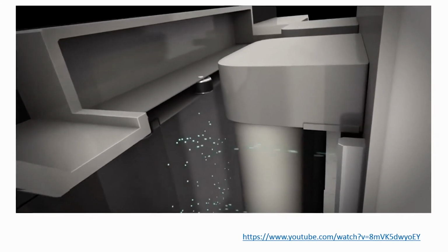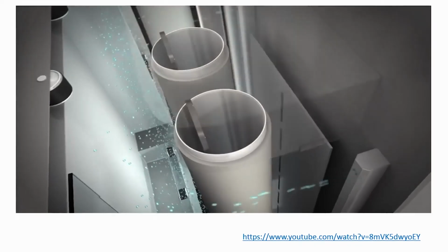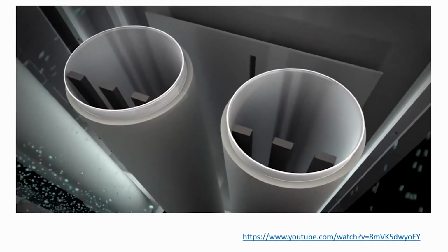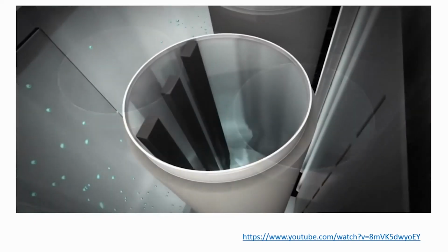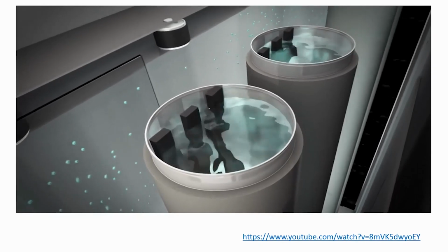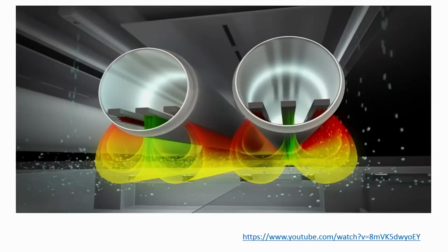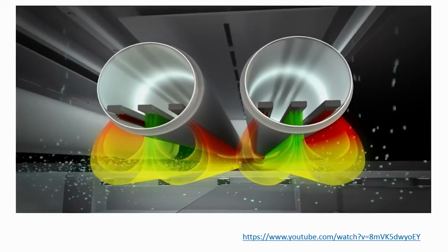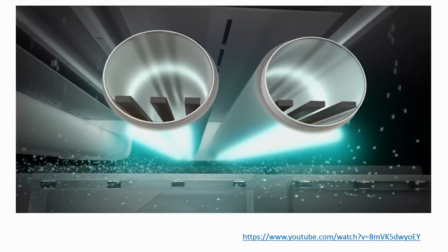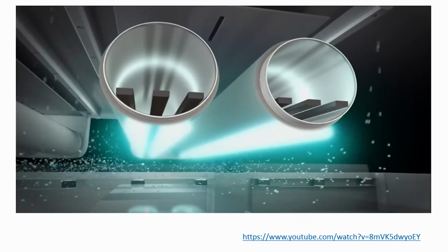Argon gas is introduced continuously to achieve a low pressure argon atmosphere. A magnet array inside the cylindrical target generates a magnetic field. The target is filled with cooling water, which will dissipate the heat generated during the sputtering process. The targets are rotating so that the material will be utilized uniformly. A high voltage is applied to the molybdenum target and creates a plasma, which is concentrated along the magnetic field.